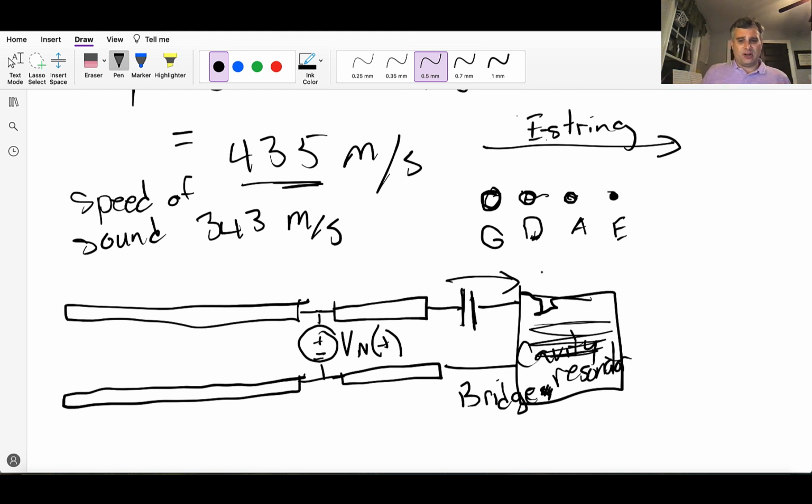You'll always hear us talking about that in antenna engineering for the rest of the course. We talk about size, we talk about electromagnetic size, not the absolute size in terms of meters. It's all relative to a wavelength. So we have that cavity resonator. We excite it. And maybe if you cut some holes in the cavity resonator, some of the electromagnetic energy would eventually leak out into the air, not unlike the F-holes of a violin that allow a lot of the sound to escape the instrument and for an audience to appreciate it.